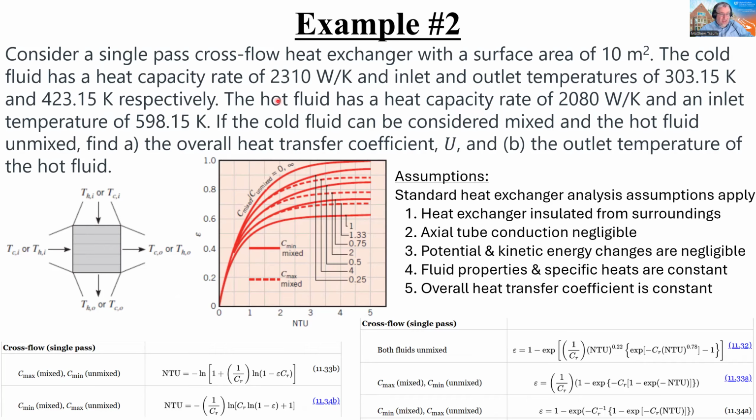Thermo too, same story. Fluids, same story. Always use Kelvin, never use Celsius or Fahrenheit or Rankine for that matter, even though Rankine is absolute, because you get into trouble by accidentally dividing temperatures that are not absolute temperatures and getting your math screwed up. So please use Kelvin. And I've already done it for you here, so you don't have to.